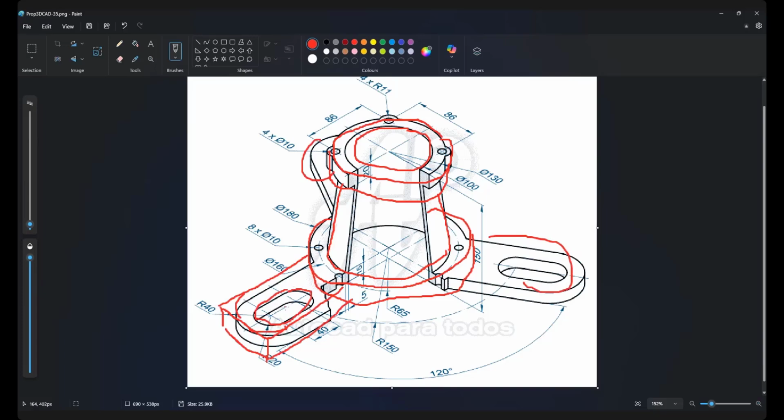Macam before you use mirror, right? Mirror. And the next one is circular pattern. You define what is the circular path, and then you select all the features that need to be circular patterned. You say the number is 3, then it's already done, here and here. You don't have to do it 3 times, right? So how do you do it? Actually not difficult. This one is not difficult, right?